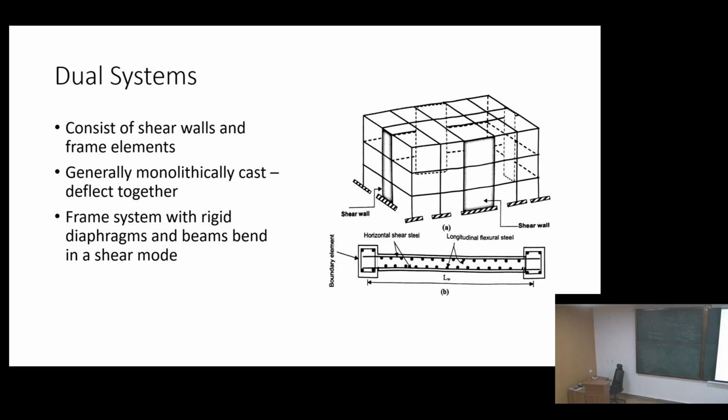Do you know what the diaphragm is? Can you be louder? You know what a diaphragm is? Act as a rigid body to transfer slab loads to beam and column. Slab loads to beam and column. With, what's the specific mode of deflection or mode of action? It's like a deep beam bending, right? So essentially it's a rigid diaphragm that transfers loads into shear walls.